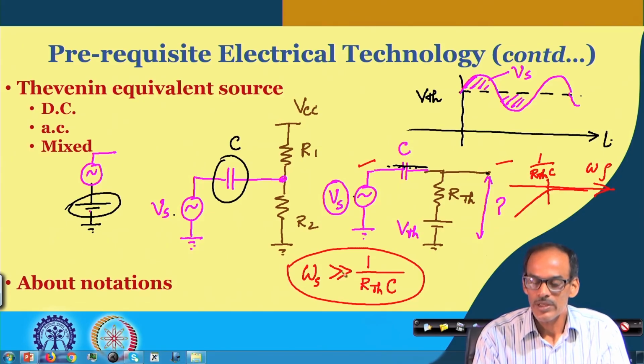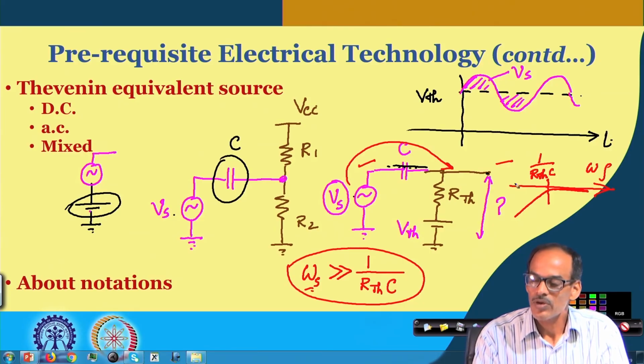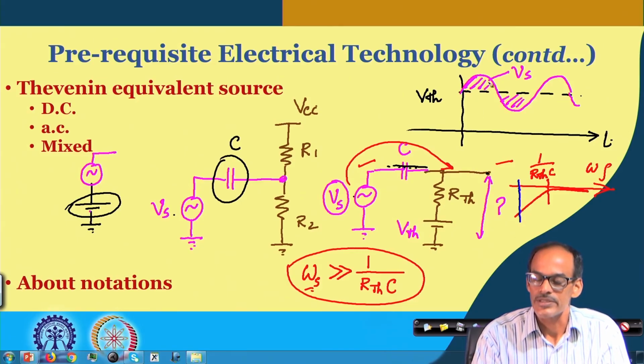So, if I assume that this signal frequency is well above this cutoff frequency, then you can say that practically the entire signal amount is coming through there. So, that is how we are doing. On the other hand, if you violate this condition, say, for example, if you have a signal component somewhere here, which is less than this one, obviously it will have huge attenuation. So, you may not be getting this nice signal there.